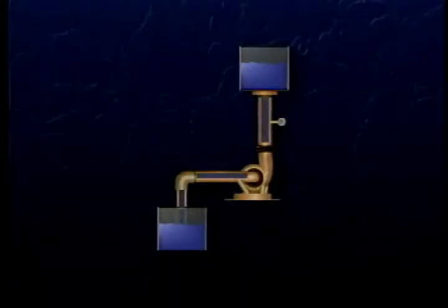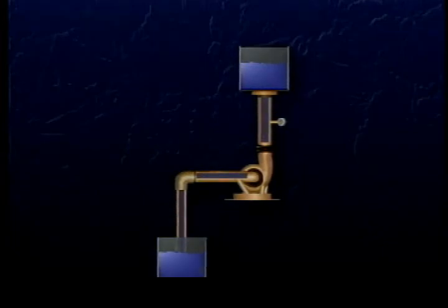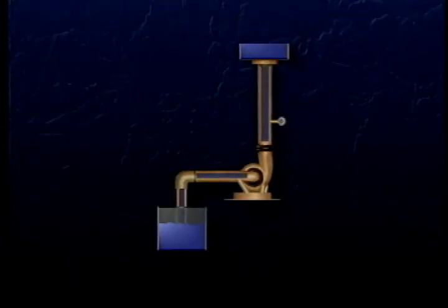The important thing to understand about static head is that the work a pump must do can change a lot if there are changes in the static head. For example, if the level of the suction side is lowered, if the discharge side is raised, or if a heavier fluid is being pumped, the pump will have to work harder.